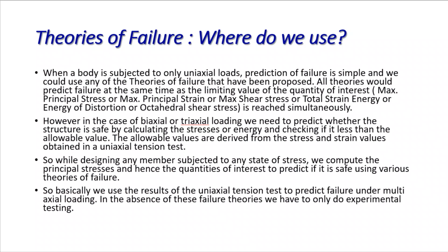However, in case of biaxial and triaxial loading, we need to predict so that the structure will be safe. In case of mechanical, we want the machine to be safe. Check whether it is less than the allowable value or not. If it is exceeding the allowable value, we can say that material is failing according to this theory. The allowable values are derived from stress strain values obtained in the uniaxial test.